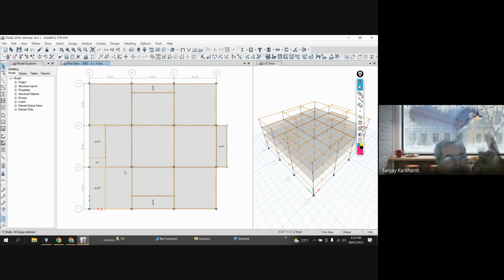Now I can straightaway select 1, 2, 3, 4, 5, 6, 7, 8, 9, 10, 11, 12, 13, 14, 15, and I will check that 15 because I don't want to get confused. So I will recheck over here: 15 shells, that's why I counted while selecting. Okay, so only the 15 shells are selected, and then I will go to replicate. Now this is on second.